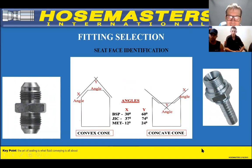I just expect, now see there? Convex and concave. So JIC is convex, BSP is concave. So you can see how that goes, and then they match on the opposite. So the female on the JIC will be concave. It'll be the opposite. I'm not going to go any further because I know it'll just confuse you. But believe me, you'll understand it when I show it to you.